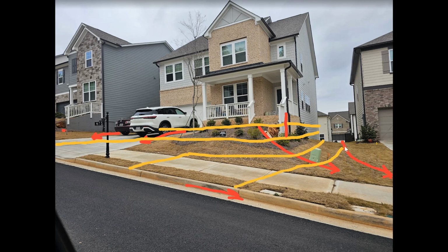And again, we've got a little bit of swale from that high point in between those two houses that is bringing that water from that high point to where the driveway and right-of-way, driveway and sidewalk meet, being the low point right there. And just sketching out how this would look if we were doing the roads and what the contours would look like. And so those contours do follow the gutter uphill, and then it hits the gutter and goes out into the street.